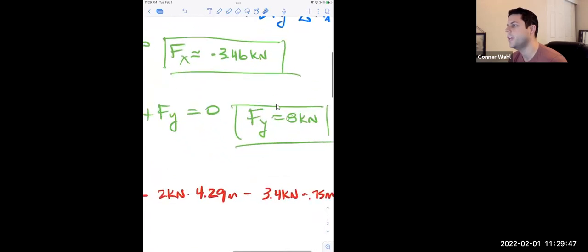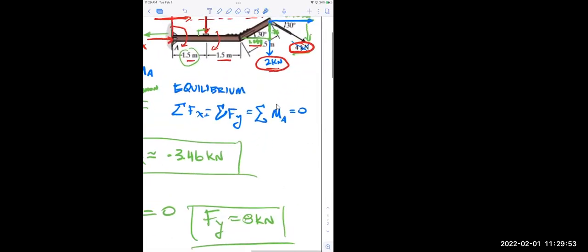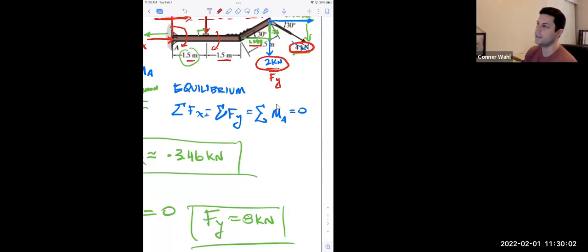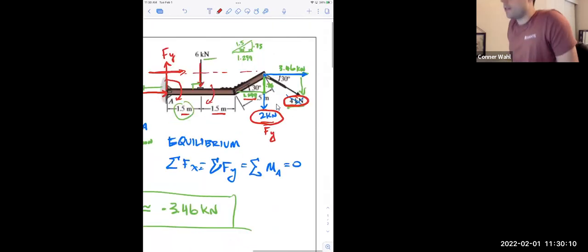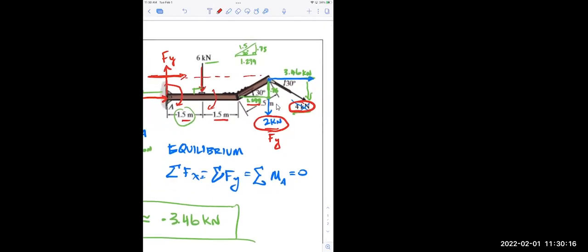I get it now. So we had to do the y distance away. Yeah, so just like the cross product, this is a force in y, and we ended up multiplying it by the distance in x, because that's perpendicular to that. Okay, my bad, I got it now. And I think this 3.46 is even harder to see unless you visualize it as I pointed out, moving over to this location, because that's really where it is. And so it's this far away from A, and that's where that 0.75 calculation comes in. That's how far it was away.